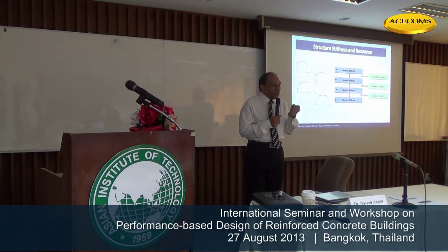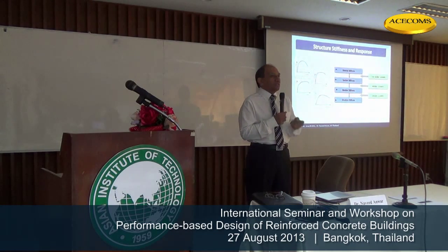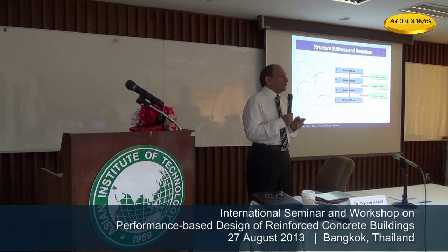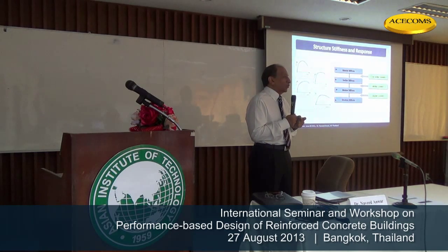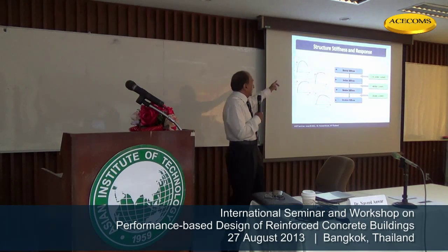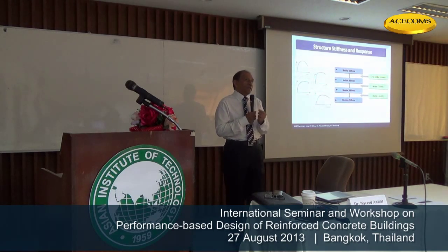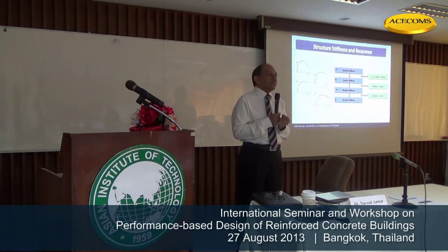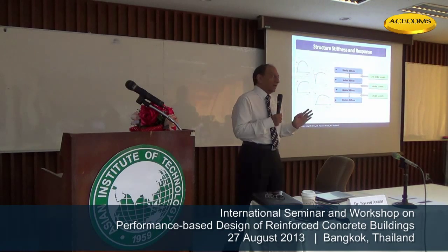So right from the start, the material is nonlinear because the stress-strain curve is nonlinear. There is no single value of E that we use in the programs. It means nothing, because E is changing all the time. When we use E in analysis, it actually has no meaning because we are just using one arbitrary value at some point, maybe the start point. But after some deformation, that value is not valid anymore.